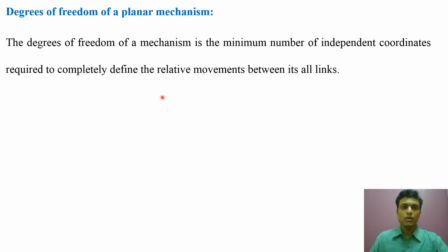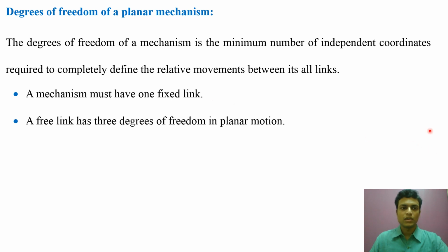Now let us note some important concepts on degrees of freedom of a planar mechanism. We all know that a mechanism must have one fixed link. Second, a free link has 3 degrees of freedom in planar motion. Let me explain this.